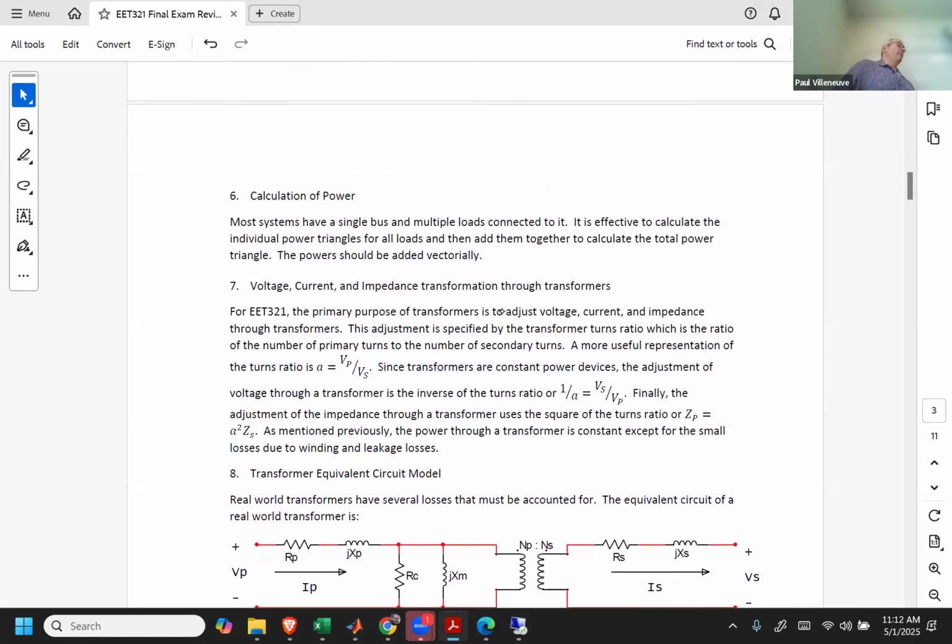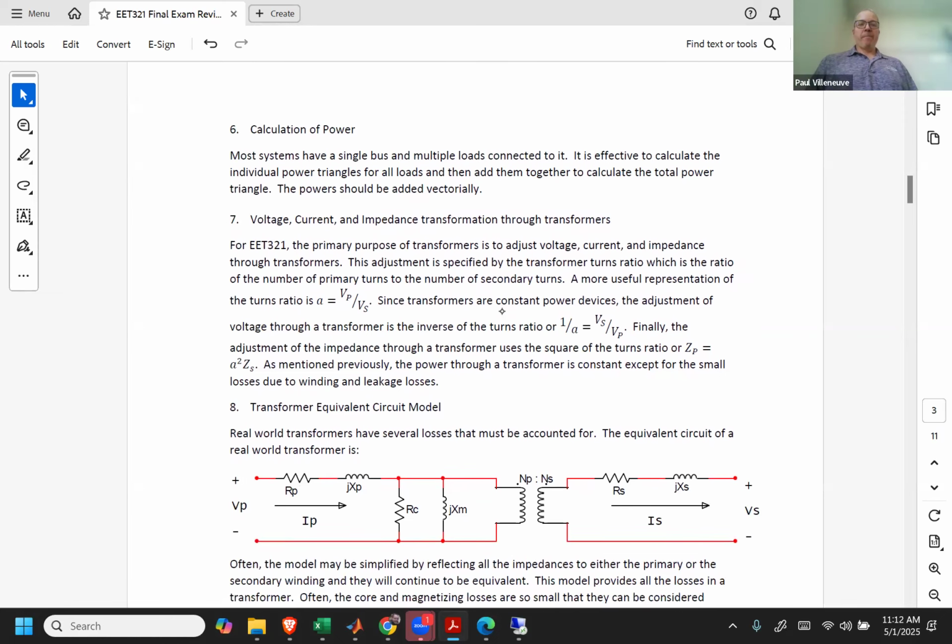When you calculate power, power is just vectorially added. So if you calculate the power for one load and another load, you just sum them together algebraically. Super, super easy to add. And so that's what we do when we do calculations for loads in a building or on a panel. We figure out not what the currents are, because the currents go in all different directions, but we figure out what the power consumed by each load is, then we add them up. Makes the calculation really easy.